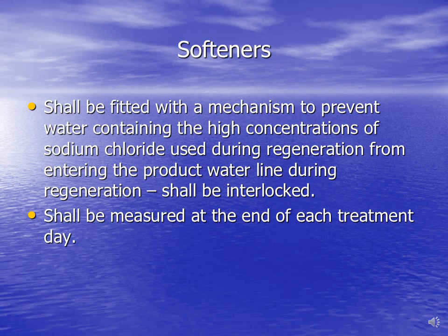The hardness shall be measured at each treatment day. This is to verify that the size of the softener that we have can accommodate the full water need, or full ion exchange need, for your treatment day. If you were to measure that at the beginning of each day for the hardness, it will always be good because it regenerated the night before. You would know whether or not it can sustain your full day's operation by checking at the end of each day.